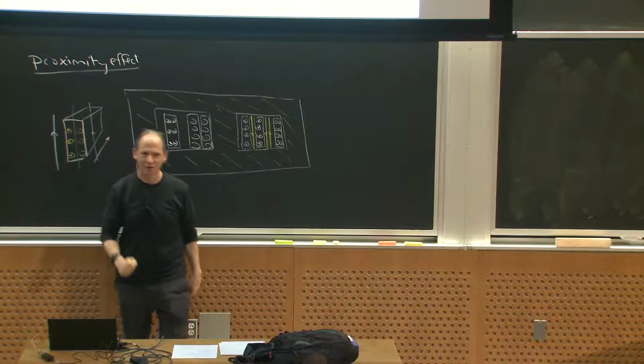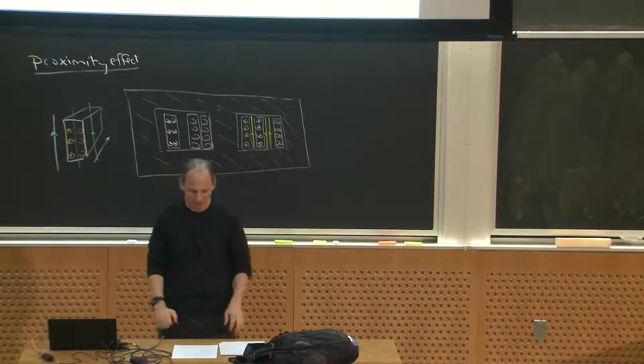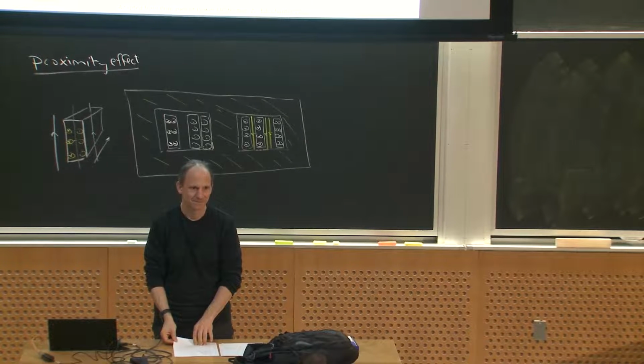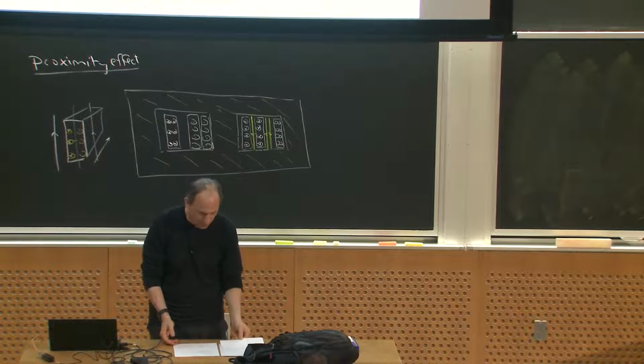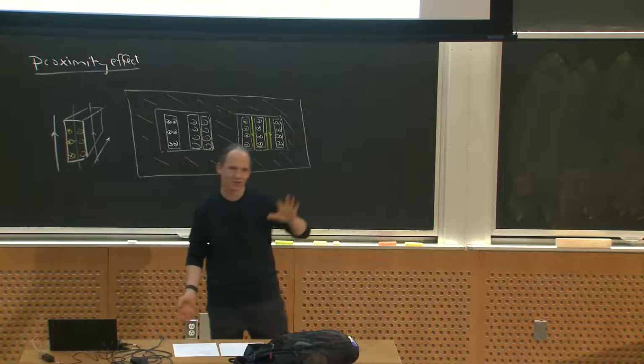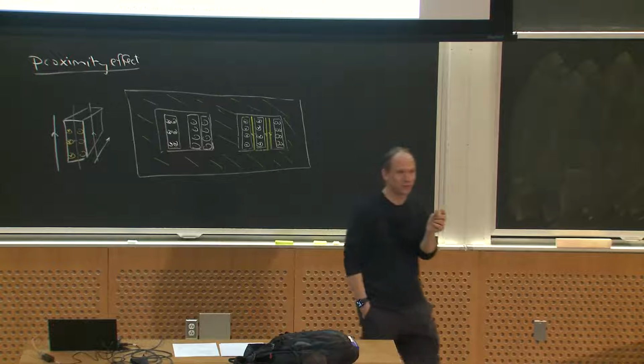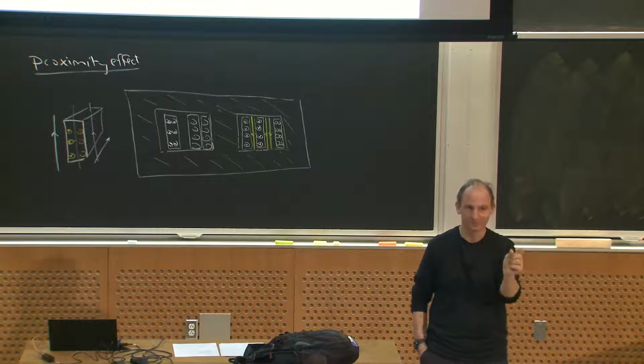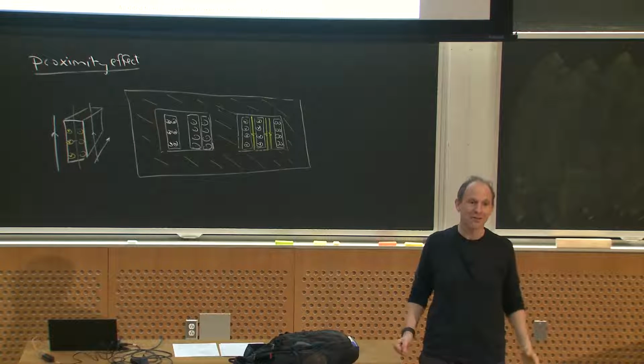Don't worry about it if you're carrying mostly DC. It's not a problem. It's just something for you to know about when you start to think about signing really high frequency things. Start at 50, 60 hertz. Well, okay, so the skin depth at 60 hertz, and this depends again on temperature, is on the order of 3/4 of a centimeter. So if you were talking a really mondo, like you wanted to carry 10,000 amps,